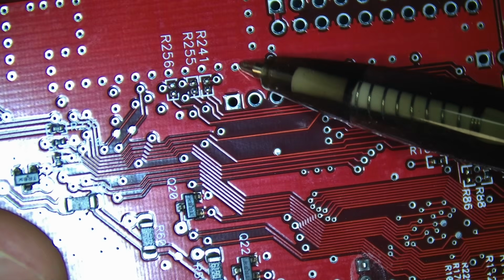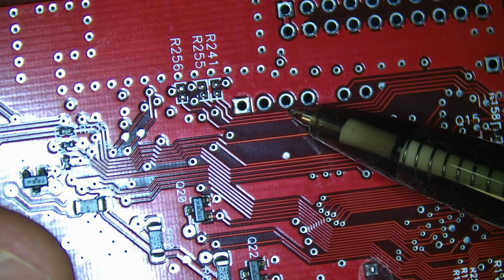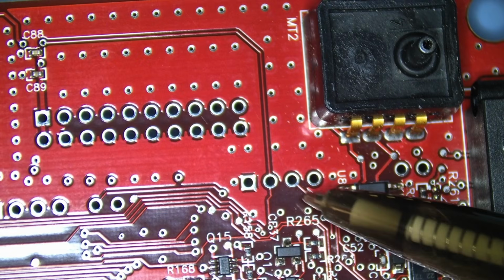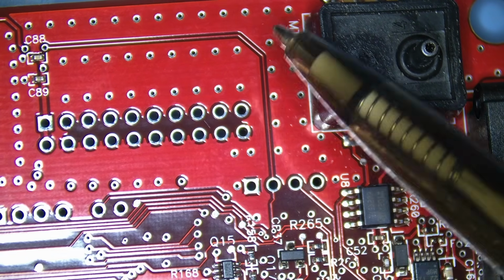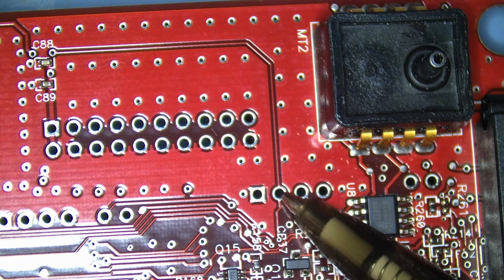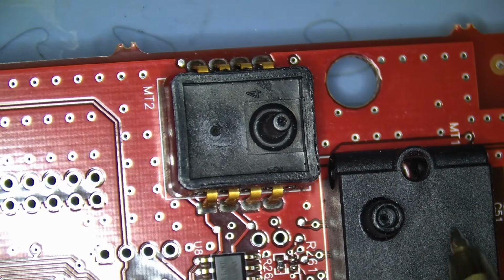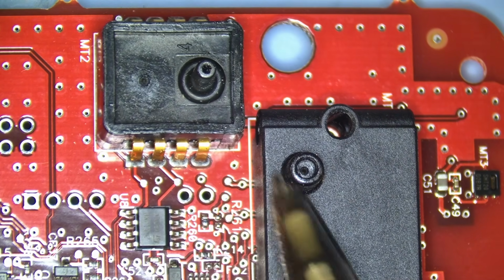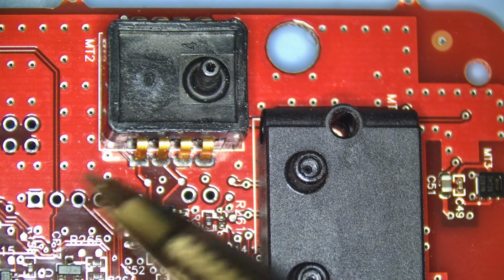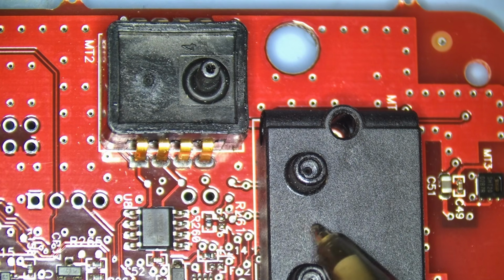You can also see how it's connected to this large plane right here, which is the ground plane. And here are those other two vias that are the RX and TX. Now this one over here, I could be wrong because look at this. It goes over here by this controller chip, and the other one comes over here to a capacitor and over here. This one here might be for these pressure sensors. You see that? So if that's the controller for these pressure sensors, maybe if you're programming it, maybe to also calibrate it, because you have to set the gain levels for these sensors.